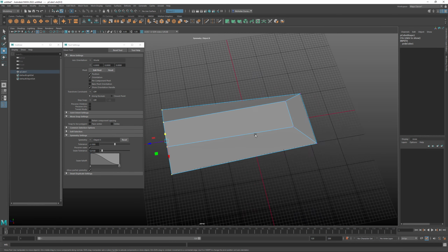And if you want to extend that, I just put like another 0 in this thing, and it can push out even further. If you want to have it go really far, you can maybe add 2 zeros to that. And then this black junk that's kind of drawing on here is the near clip plane. So I might put that at 1. Depending on the size of these objects, I'm working on a fairly decent scale, so you might have to go even larger with that. So you can see if I do 10, it fixes that problem. So I usually start with 1, and if I'm really looking at the object far away and it's really having problems with that, then I'll put the near clip plane to 10.